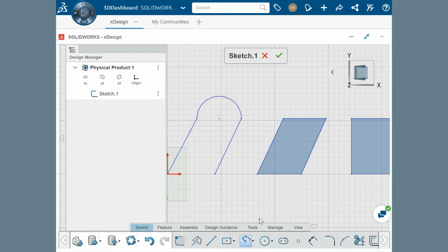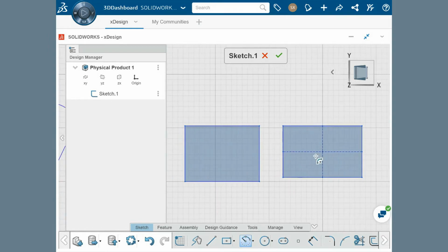The center arc is created by first clicking to place the center point of the arc, then clicking in 2 more locations to define the endpoints of the arc. Note that the distance between the first click, which sets the center point, and the second click, which sets the first endpoint of the arc, will determine the constant radius used for this arc.